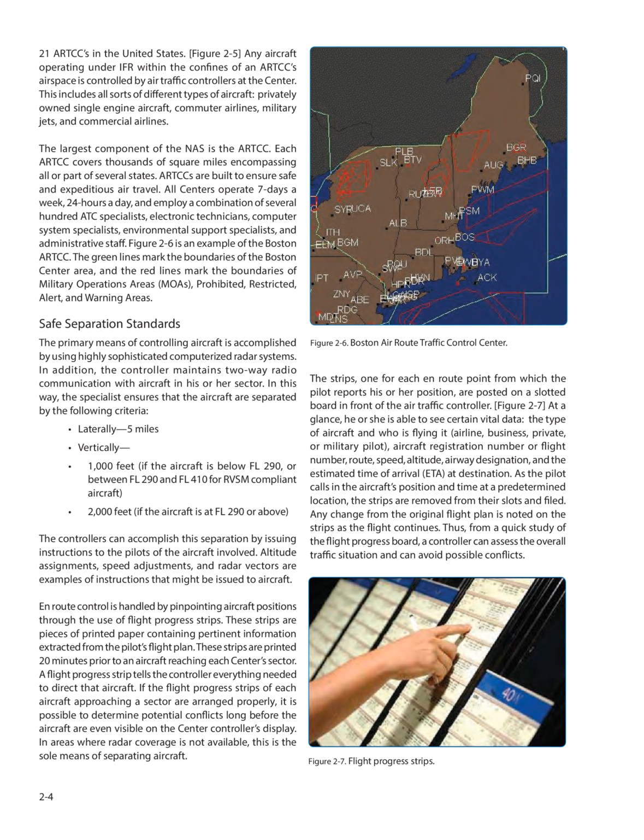The controllers can accomplish this separation by issuing instructions to the pilots of the aircraft involved. Altitude assignments, speed adjustments, and radar vectors are examples of instructions that might be issued to aircraft.